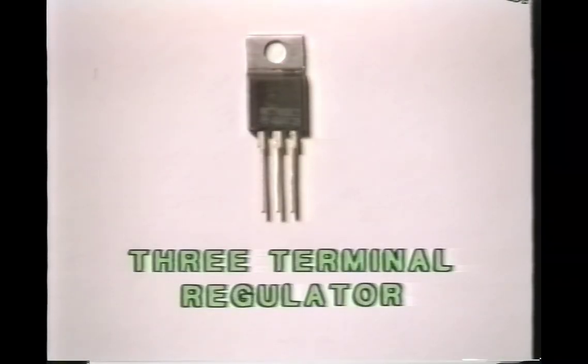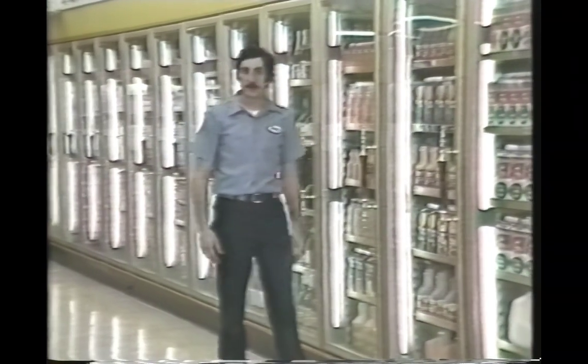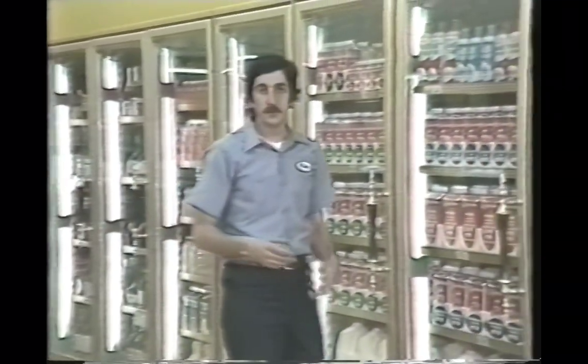The simplest type of voltage regulator used in games is something called a 3-terminal regulator. And this is a popular 3-terminal regulator. Notice it comes in a TO220 package, the same package that we saw earlier as a transistor package. However, this is a voltage regulator and it's actually an integrated circuit. You remember we looked at all those different types of transistor packages? And remember that they had different transistor outline numbers, TO3 and TO220 and so on.